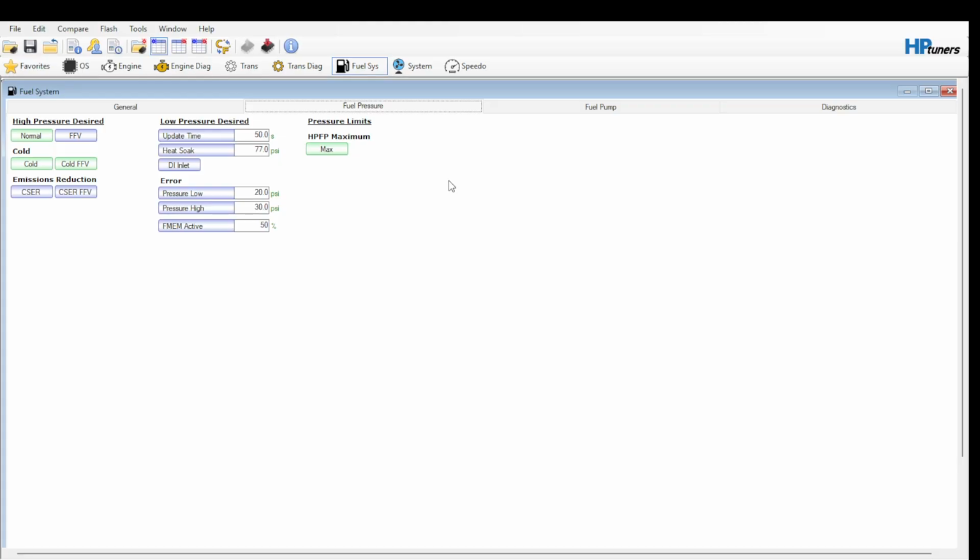fiasco. I'm still trying to figure out the electrical work myself because I'm a tuner, not an electrician. But I probably have it figured out, probably. But I'm also schizophrenic with it, right? If I notice that the sensor ever reads 0 when the boost gauge doesn't, I don't like that, right? Because what can happen if you get an expected fuel flow that just quits, right? Well, now the engine's running lean at a high output of power. That's not smart. But that's what I would recommend.